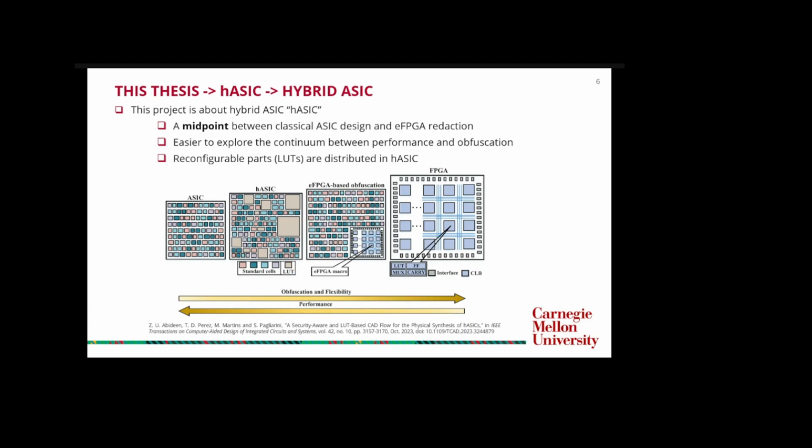We have eFPGA, we have a hybrid ASIC that we studied, right? So just to recap, we are using here only the lookup tables, so if we classify this one, this is kind of LUT-based obfuscation also. And then the goal was that we try to provide a flexible platform where the designer can meet security and PPA trade-offs, right?